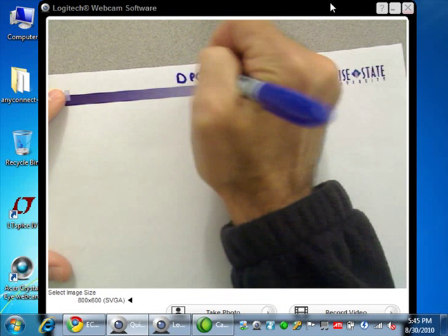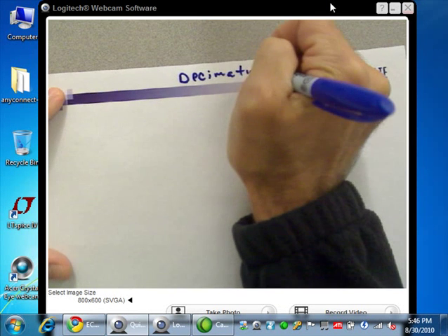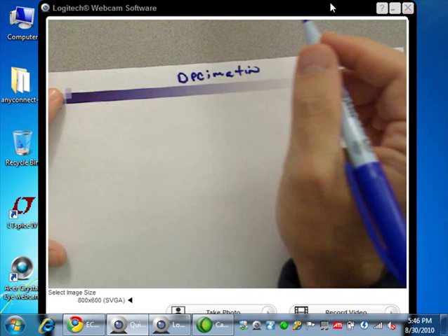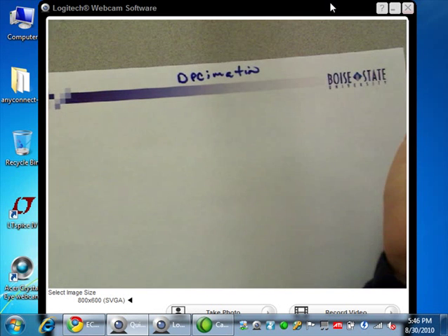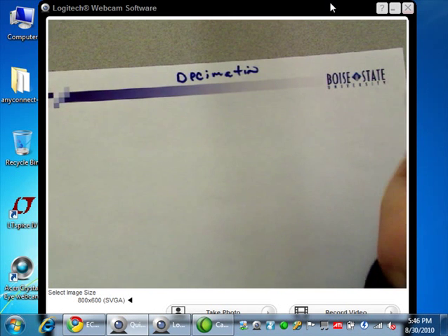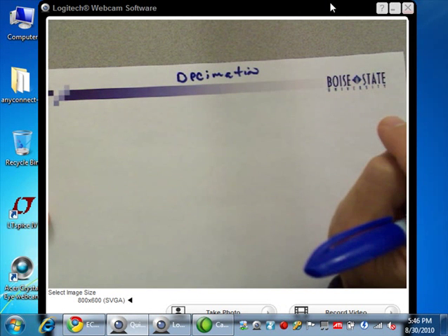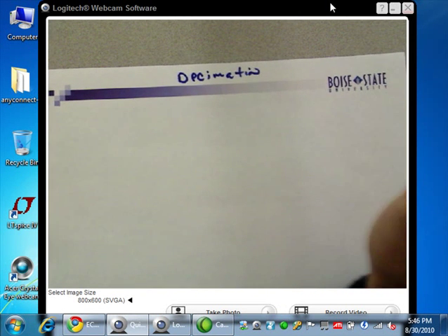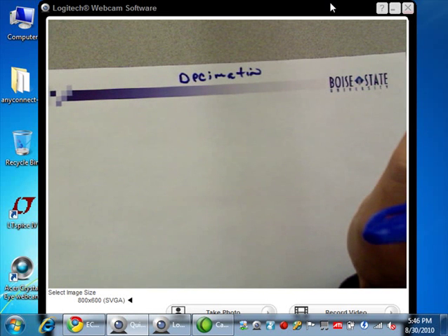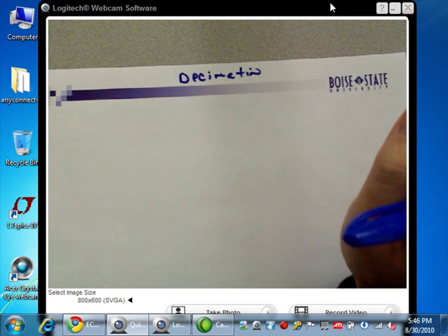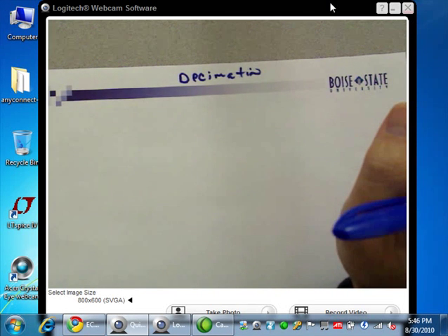So now decimation. Why would I want to use decimation? If I'm storing the data, it's less data to store. If I'm transmitting the data, it's less data to transmit. If I want low power, I don't have my multipliers running at as high speeds. There's lots of reasons I want to slow things down. But if I slow things down, I also have to reduce the frequency content of my signal. I can't have very high frequency signals or else I end up with aliasing.